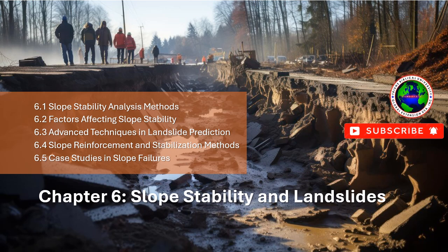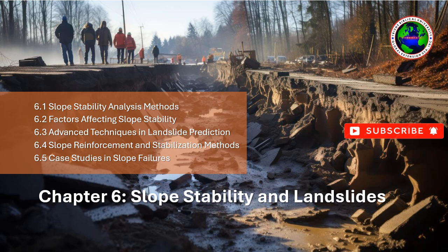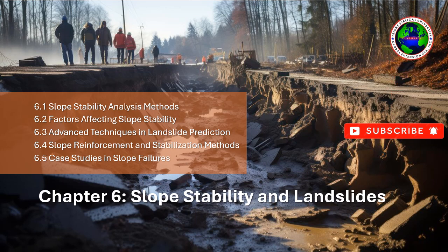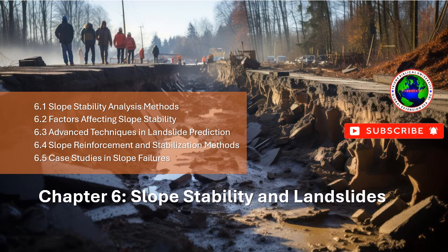Geotechnical data logging and alarm systems. Real-time data collection. Systems continuously monitor changes in slope conditions, such as displacement or pore pressure, and send alerts to engineers or operators if a threshold is exceeded. These systems can trigger alarms, allowing for timely intervention and evacuation in the event of an imminent landslide.